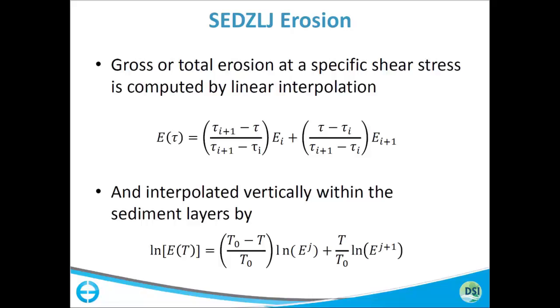The approach here kind of follows Guy's approach, which is this fractional split here. This is the amount of material, the mass of material that's making it into suspended load versus your total erosion rate. So it's taking that erosion rate and starting to split it. Well, obviously, the fraction that doesn't go into suspended load goes into the bed load component.